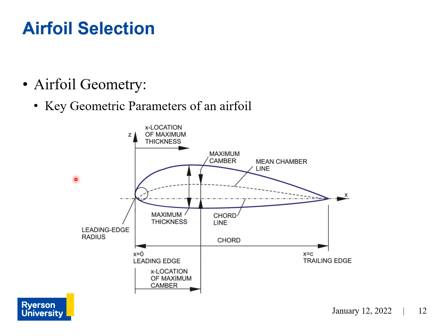You should note that thickness has a direct effect on the skin friction drag of an airfoil. And again, camber affects the lift produced by the airfoil, and the lift-induced drag as well as the aerodynamic pitching moment are affected by the camber of an airfoil.